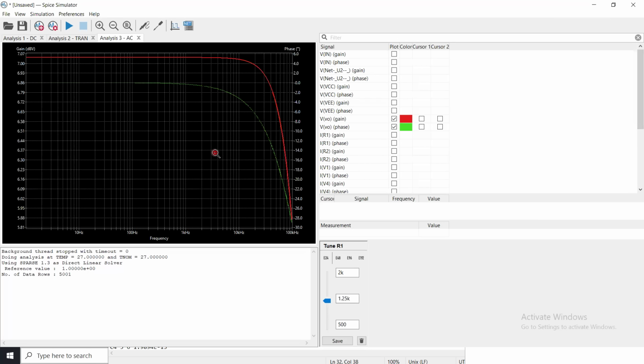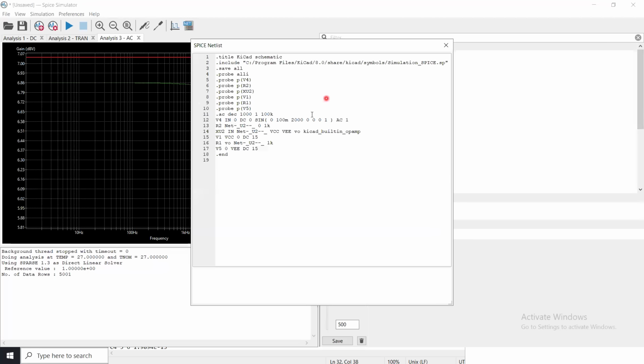So we have successfully designed a real world circuit of operational amplifier in a non-inverting mode using the KiCad software, and we also can call the NGSpice netlist. We know how to call this. This is a netlist. You can just save it as a .sp file. It's a SPICE netlist. Open ngspice, just a command-based software, and just plot the same DC transfer curve, same time domain simulation, and same frequency response without KiCad.